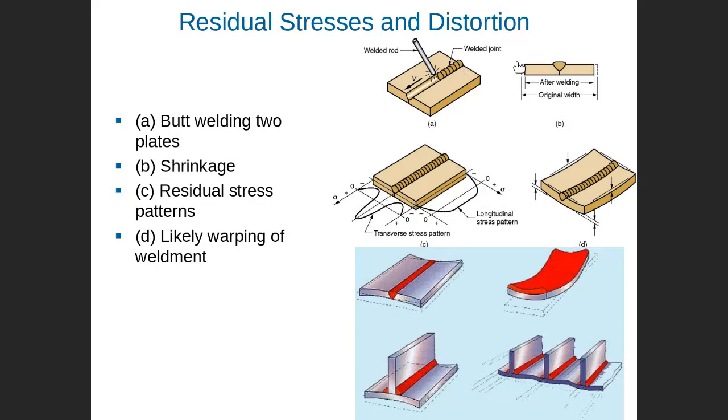as you can see here. Because of heating and melting exactly in certain locations, not everywhere, with very localized heating, melting and solidification in these areas, you expect to get a very high thermal residual stress exactly in this location. After solidification, distortion usually happens. Different types of distortion actually happen in welding, as you can see.